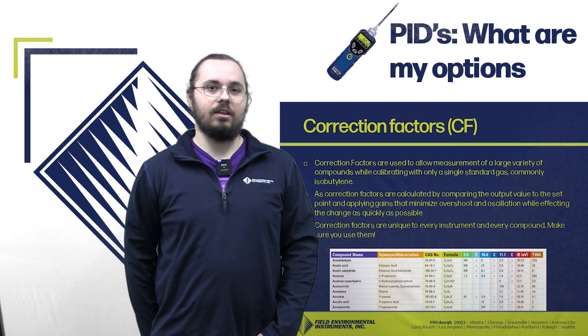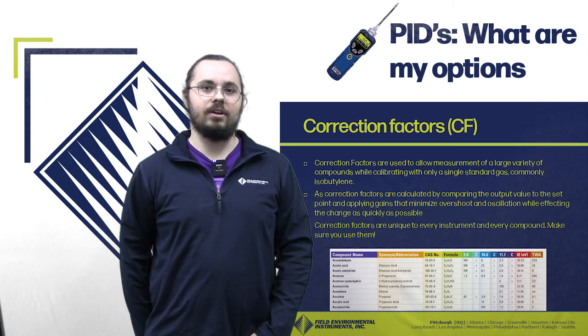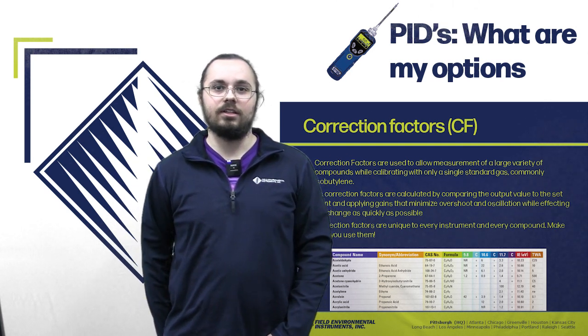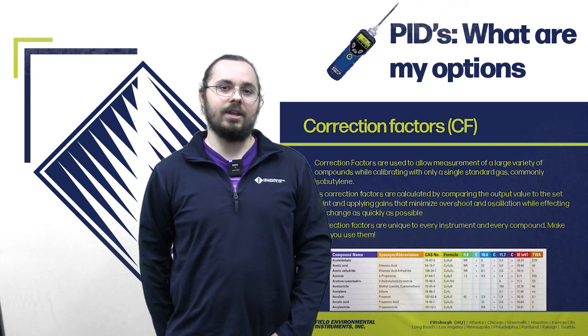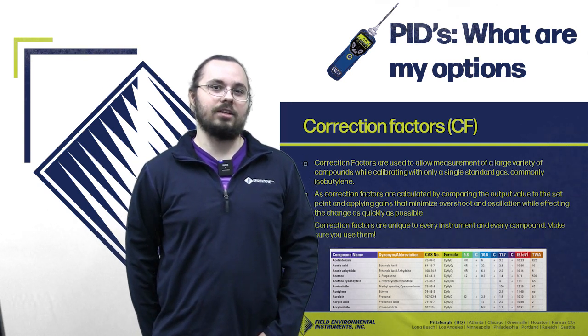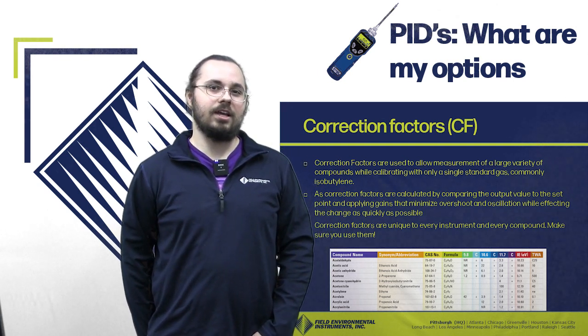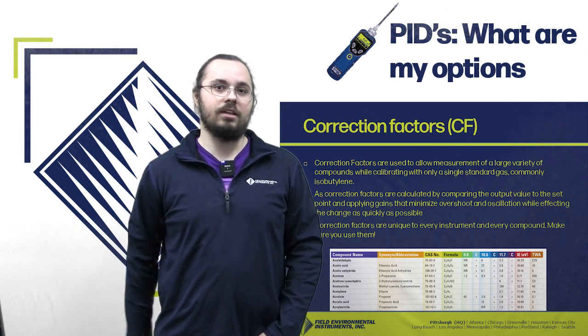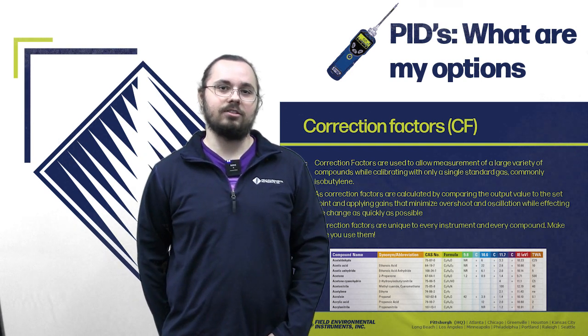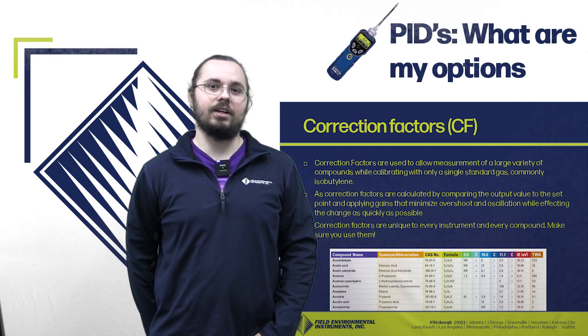Remember, these are unique to every instrument and every compound that you'll find. So it's important to read your manual and know which correction factor to use. A lot of times instruments will have a built-in system for correction factors, so you just need to select whichever gas you're going to be detecting out in the field.